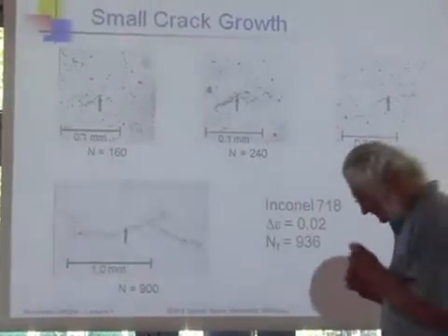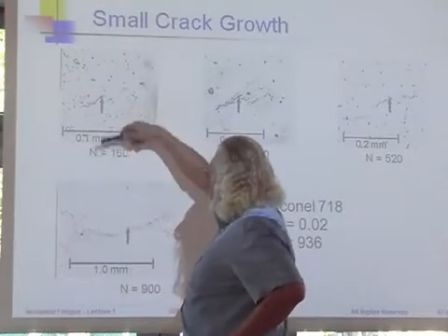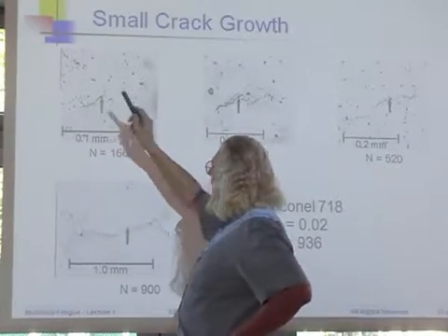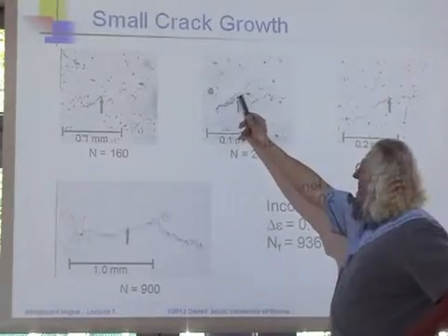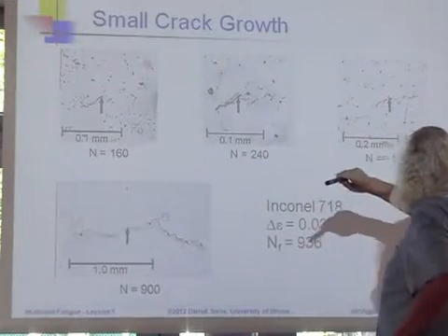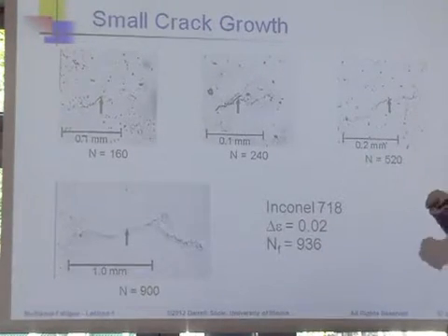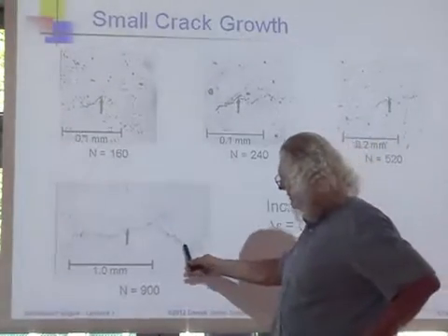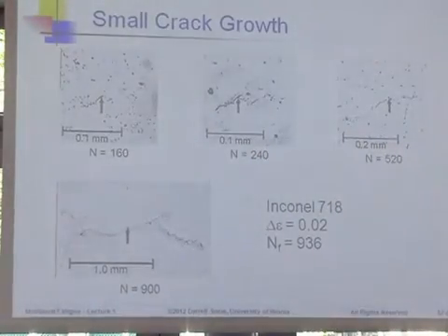So let's just look at the beginning. So at the beginning you see this stuff. Of course, tension is loaded in this direction. You get some idea about size. So that's 100 microns. And smaller and then shear. And then as things progress, it's pretty complicated. Really, so you get that shear, and here's some stuff not yet linked up, and there's some stuff over here, and you can see with time, there's where it originally started, and this is growing in shear, and then out like that. And by the time the crack gets to be a millimeter or so, this is what it actually looks like. And that's what every real crack I see looks like in the lab.